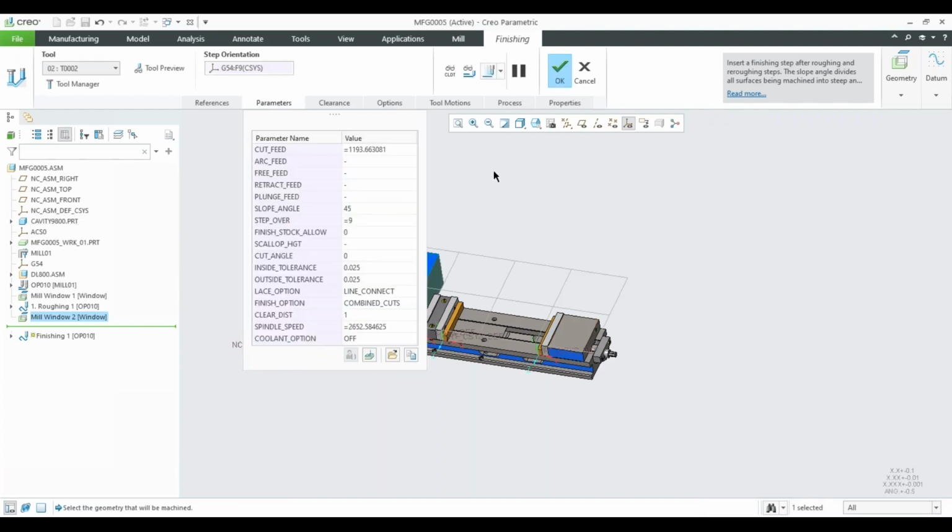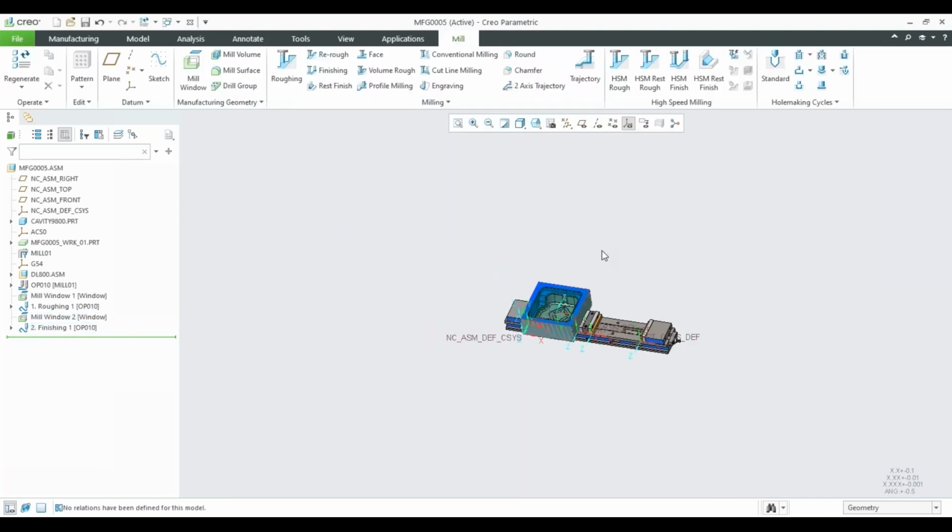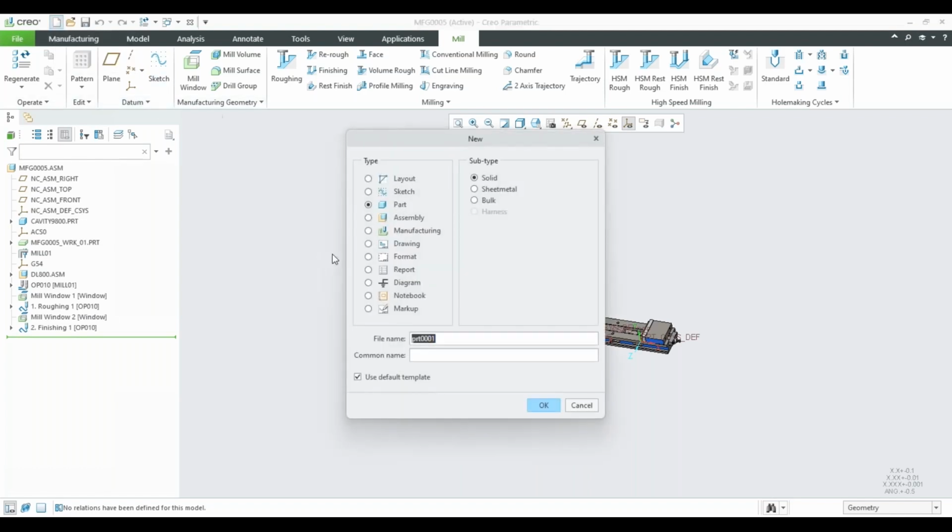Okay, so we're quickly running out of time. There's one thing that I sort of want to end up with, you guys. We talked about the workflow that you need to follow. So we're taking the part and then we design that, then we create our core and cavities from that part, and then we machine the core and cavities, and once the part changes, everything will update. Okay, so that's the typical workflow. But in Creo, nothing is stopping you to go outside of that.